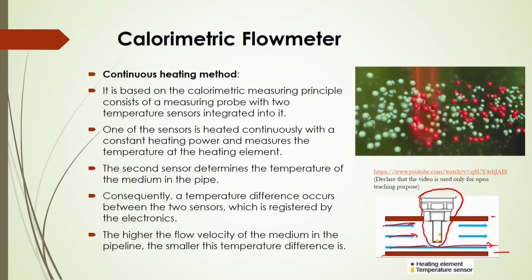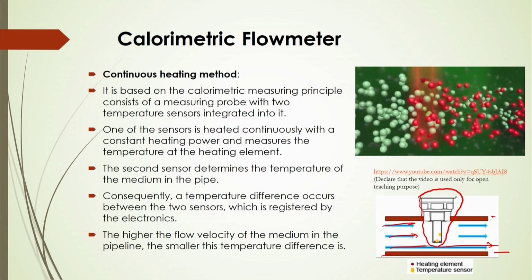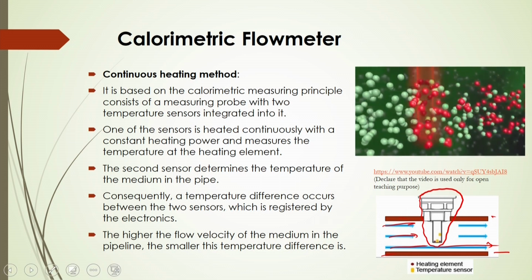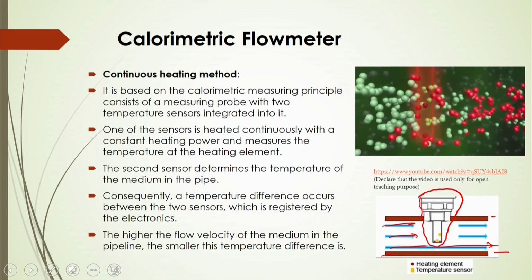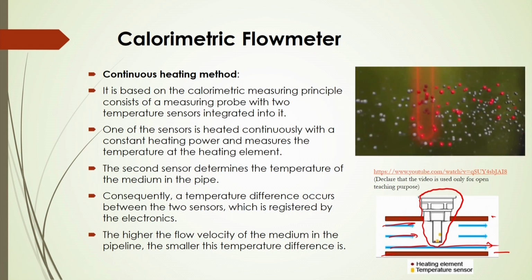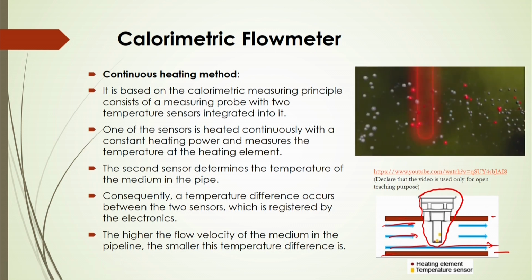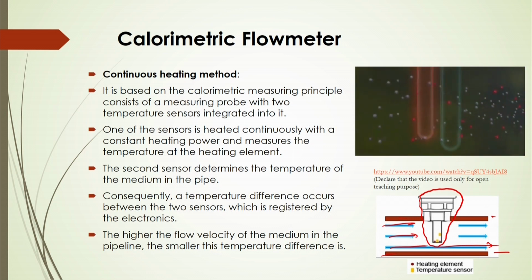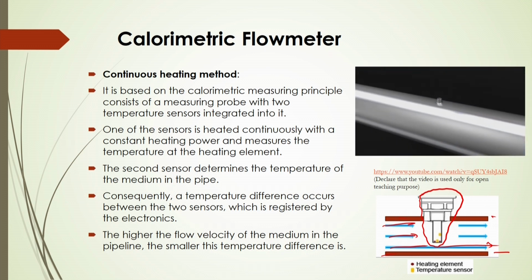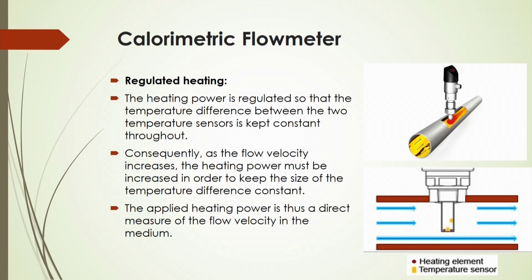Accordingly, that greater energy supply will tell you how much the flow rate is, because before you measure, you have to calibrate. By knowing a certain flow rate, you have to know how much heat energy is absorbed by the fluid. Based on that, you can obtain the flow rate from the electrical energy. Now, this is the basic principle.